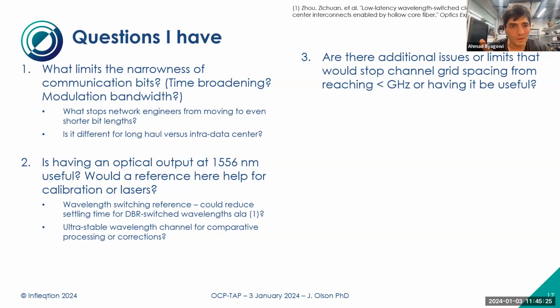I wish there were optical people here, but I don't think our SerDes are getting anywhere. Last time I looked into this, we're still at 25 gigahertz. Bijan, you can help me. We're still at 25, but we went to 50.1 or something like this, 51 point something. And while we say, oh, we are at QSFP and then OSFP and whatever SFP, we just keep putting lanes in parallel, making our way through 800 gigabit per second. It's a bunch of 50 or 25 lanes that you just keep cramming more and more of.